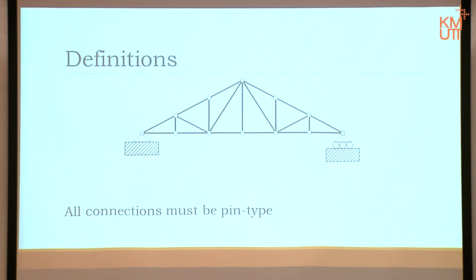The second very important scenario is that all forces must be acting on the joint, not on the member. For example, it should go like that. So basically, as we talk about the floor hanging on to the truss, it doesn't connect all the time. It only connects through the joint, meaning the slab will be down here and it connects up to the joint, leaving this member free of contact. Now, be clear? The two conditions have to be satisfied first.